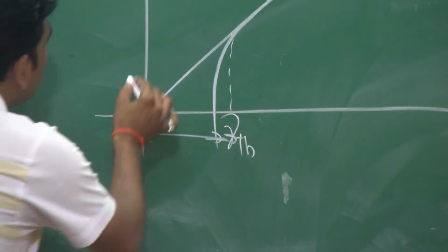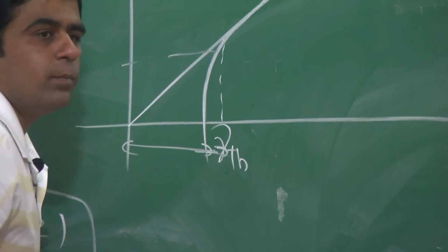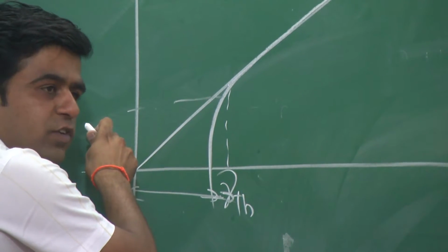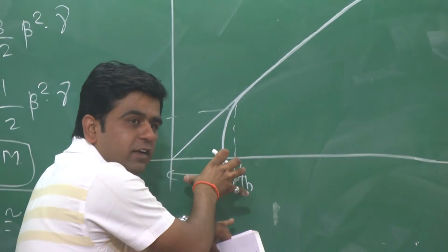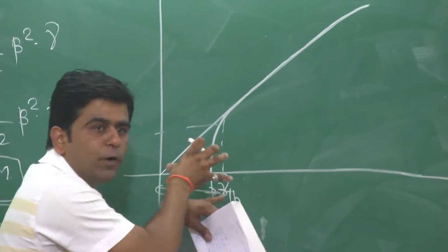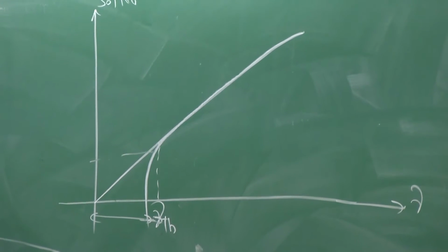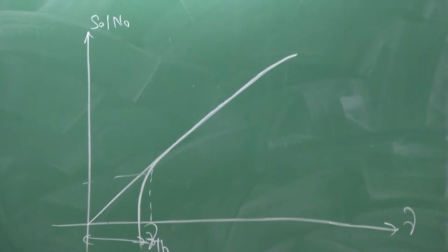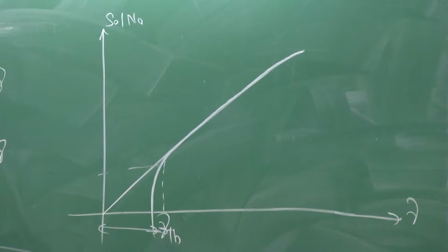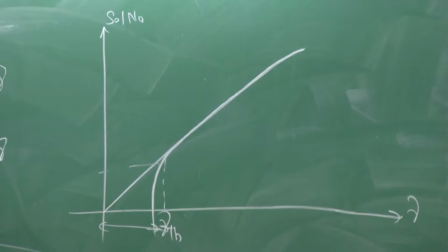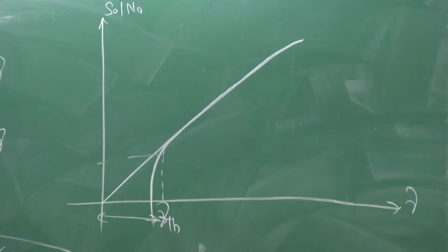Here the input signal to noise ratio is minimum, and the output signal to noise ratio is minimum. So we have to avoid this region for proper working of amplitude modulation. When working with an envelope detector or a synchronous detector above it, there is no problem. We will get a linear relationship.